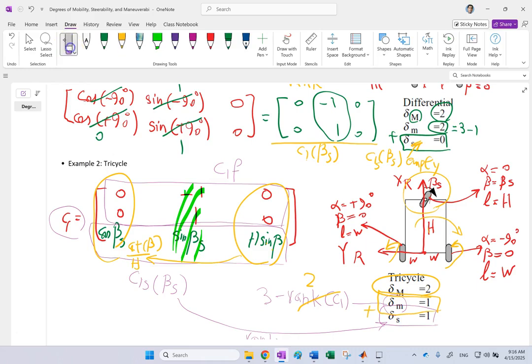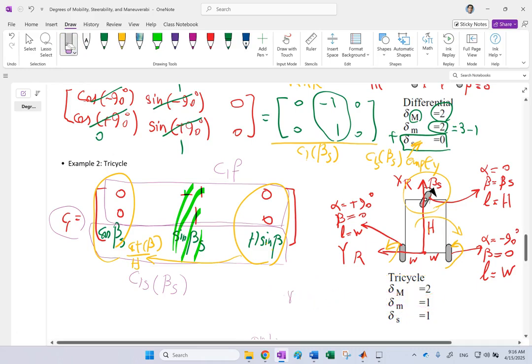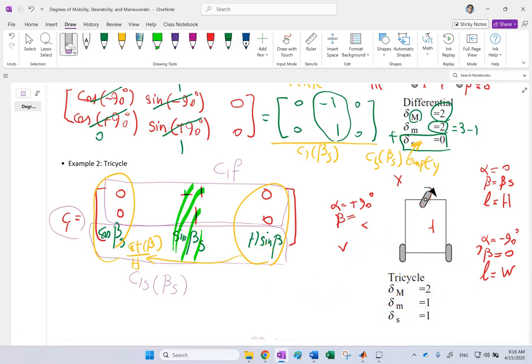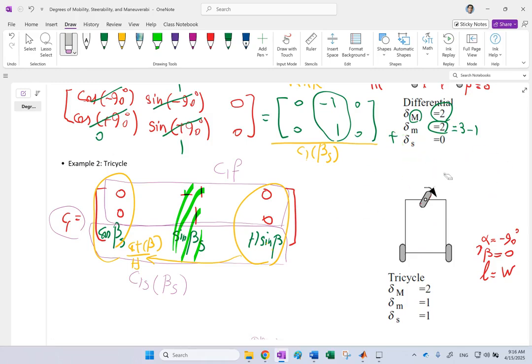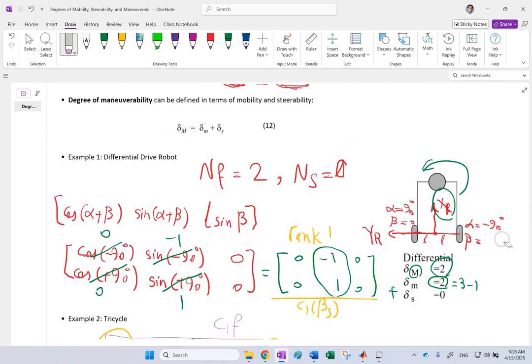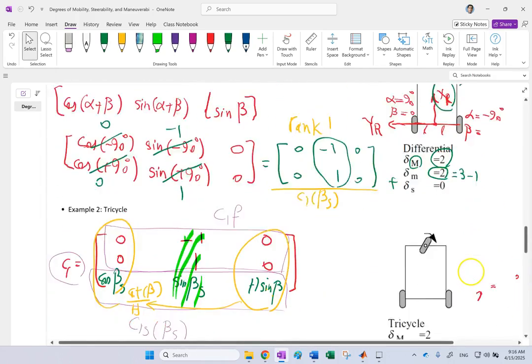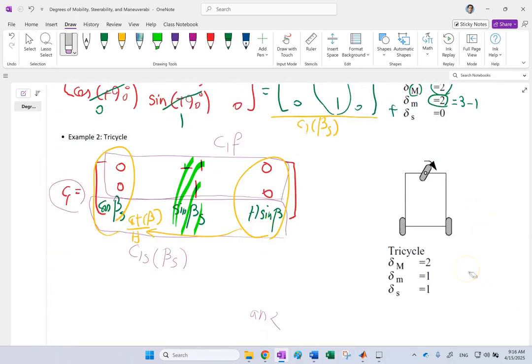So in this case, what you can do is sync those wheels together. So you don't really need a differential drive in this case. You can have them spinning with the exact same RPM. So in this case, set phi dot left and phi dot right to be equal.